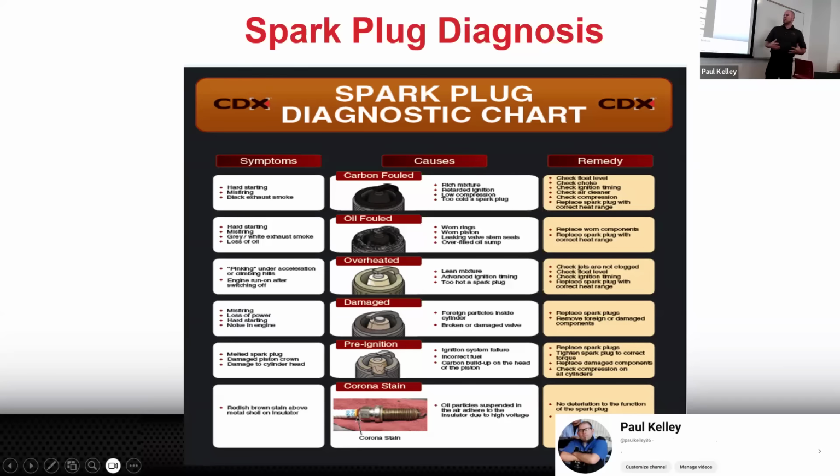But our job is to not be emotional, right? Don't be like, oh yeah, we're friends, cry on my shoulder, it'll be all right. Just throw one more pair of spark plugs in. You're looking at spark plugs, they're covered in oil. You got to know where that came from. That's your job. If the spark plugs are covered in oil, the engine's consuming oil.